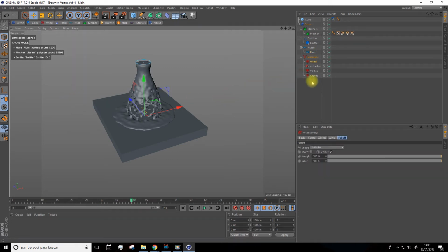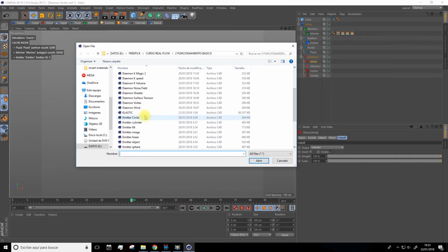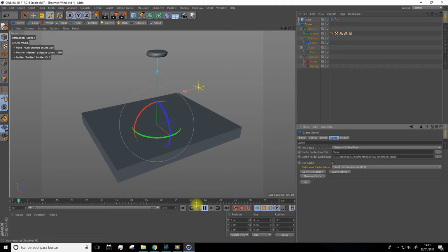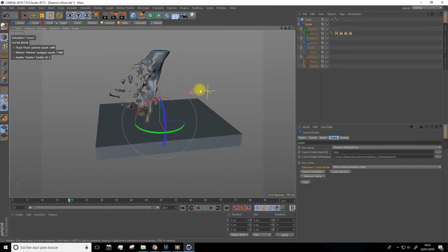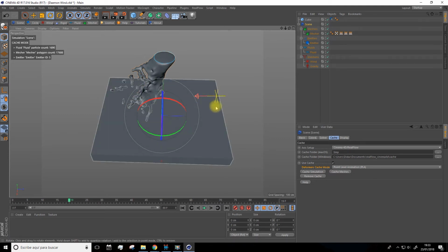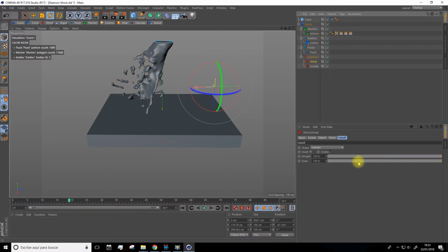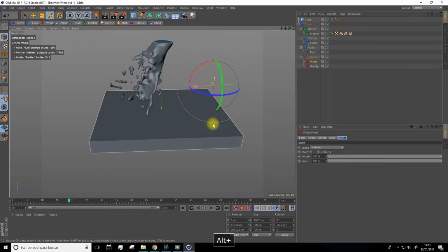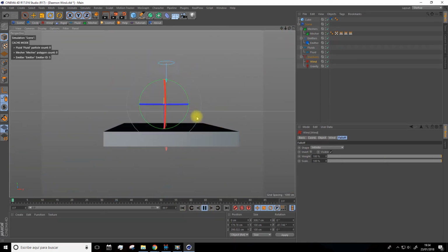The last demon is the wind, which is used to simulate wind in the scene. So here is the fluid, and I've inserted a wind force along the Z axis. So depending on the strength and the velocity, the wind will affect the fluid differently, okay?